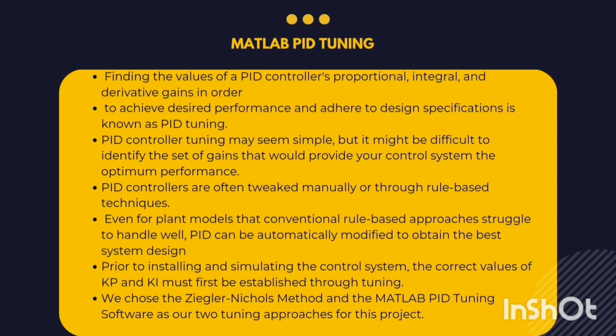On the other hand, we will be having the MATLAB PID tuning, which is used for finding the values of PID controls, proportional, integral and derivative gains, in order to achieve desired performance and adhere to design specifications, known as PID tuning. PID controller tuning may seem simple, but it might be difficult to identify the set of gains that will provide your control system with the desired performance.